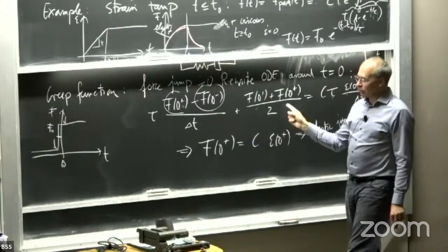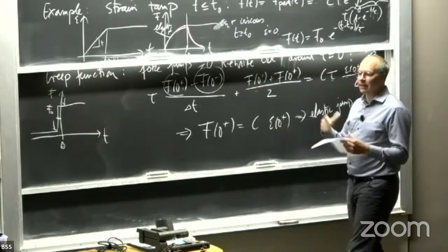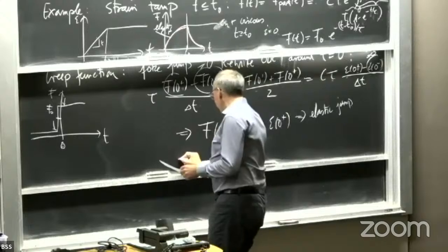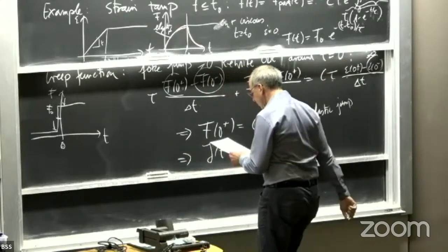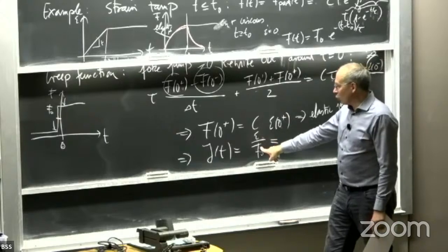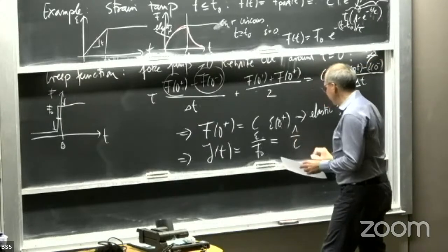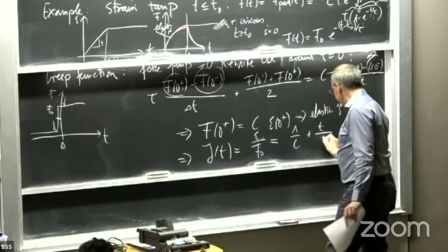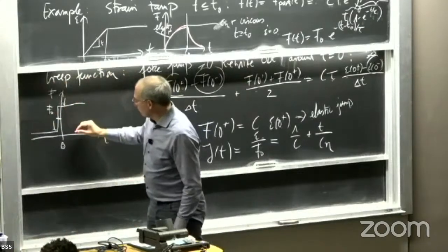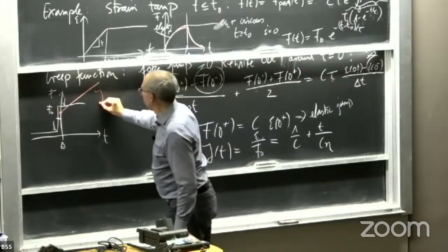And then the answer to your question is that I could do the same analysis also for the other situation. After that, the spring is basically taken care of. The rest would be elongation. From here on, you would just elongate. So the overall creep function, which is the epsilon, the strain, but normalized to the force jump, so we normalize the amplitude out, would be 1 over c, this is the elastic jump. And from there on, you would increase with t. So basically how it would look like, it would jump up and then from here on, it would go like this. This is the creep function.